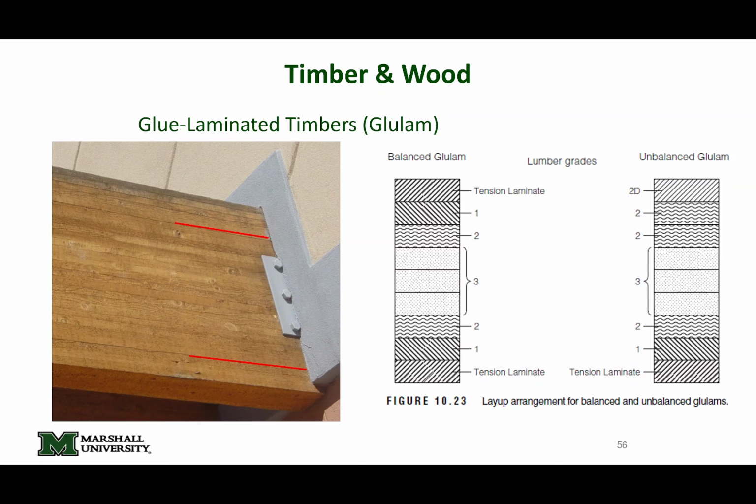Well, you have a lam here, a lam here, a lam here, and then maybe this lam, then like that, then like that, then maybe this. So you're layering the boards on top of one another, and you're scattering where the boards butt up across the span. Not only are you doing that, but you can also evenly space out any checks or shakes or anything like that. So you can get really uniform products that are really big and can support a lot of load, and it can also support a lot of load at long spans.